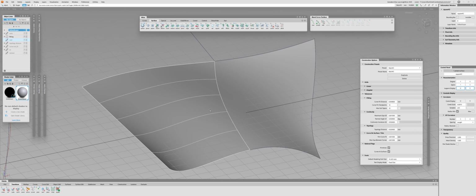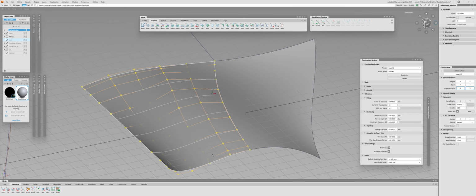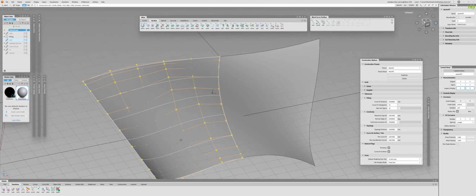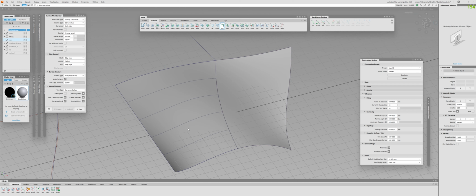Now, technically, it's supposed to work for the square tool, for the freeform blend, for rail, for multiple blend surfaces, and maybe for something else. So almost everything. But in practice, the most reliable solution, or basically the example to show you, is the fillet tool, because sometimes the square tool just doesn't care. It kind of should, but it doesn't always. But the fillet tool does it almost all the time. So it's somewhat of a buggy feature, and not just in this version, but for a few years already. But I believe it's just better to show you in the fillet tool.